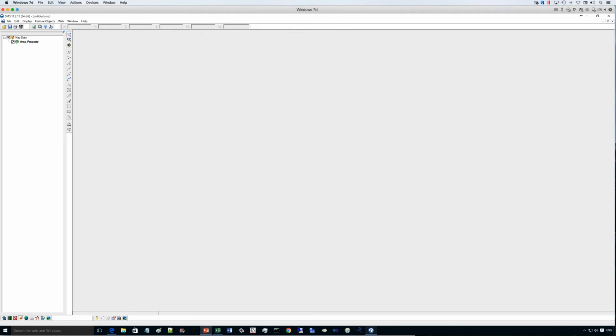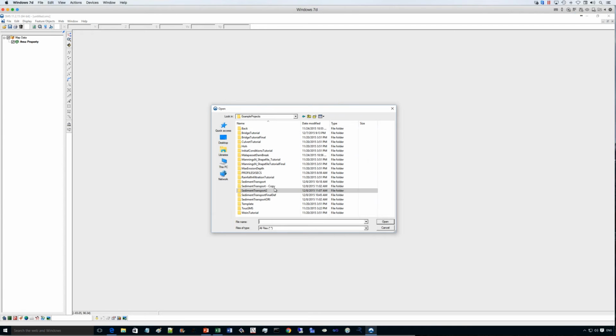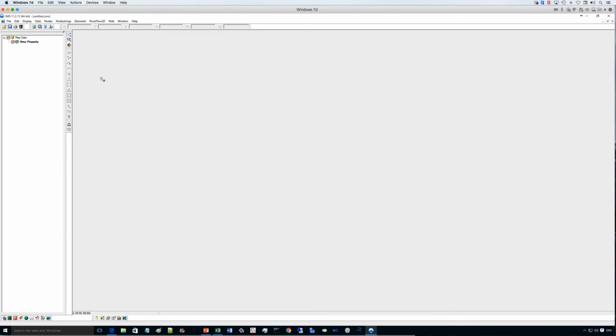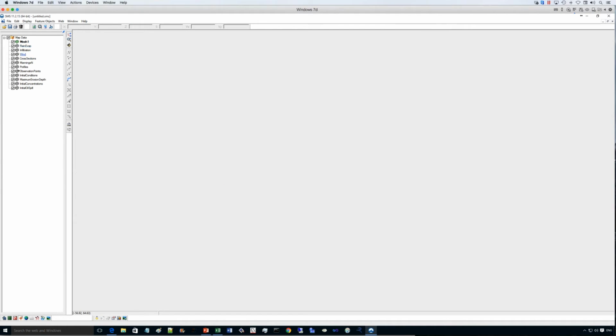Okay, so this is the SMS user interface. So what we start doing is I'm using an example that is actually a real case, and I will first load the RiverFlow2D template, and I will load also the RiverFlow2D map file that includes a number of predetermined coverages that you can use to enter data in the model.